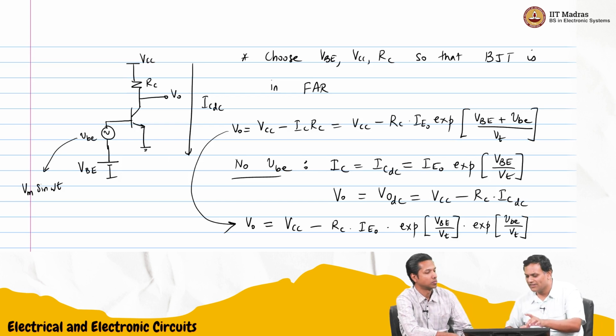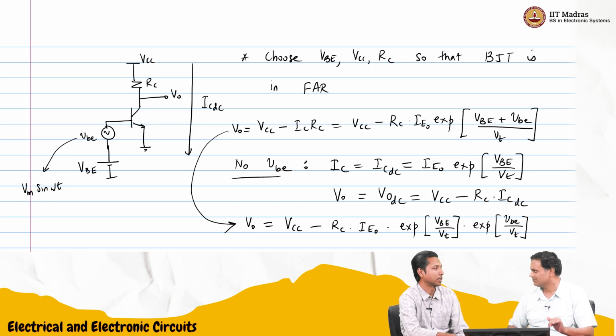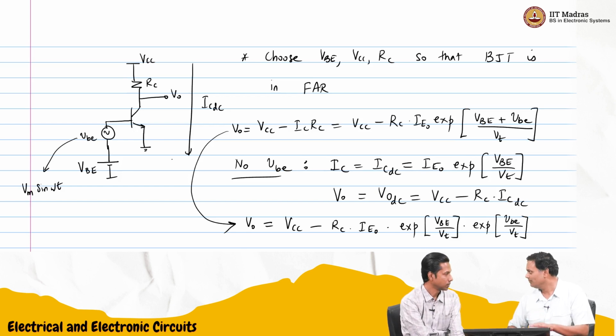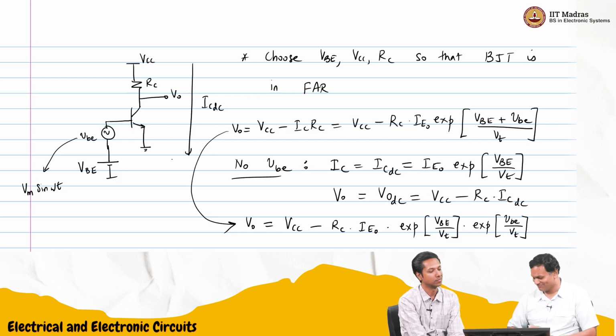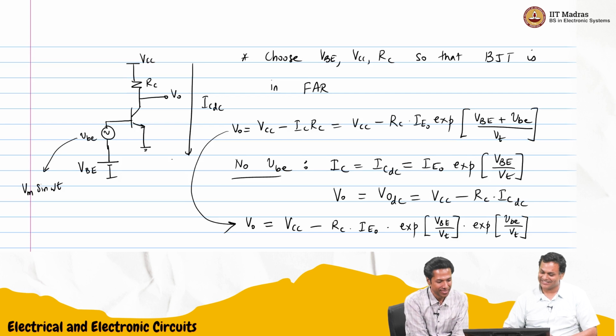Some of that will get burnt in the resistor, some of that will get burnt in the transistor. We have actually assumed that base current is 0. So directly on the collector emitter side, it will get dissipated, it will get lost as heat. So that means if you touch it, you will feel a slight temperature increase, depending on the current. That's right. Very nice.